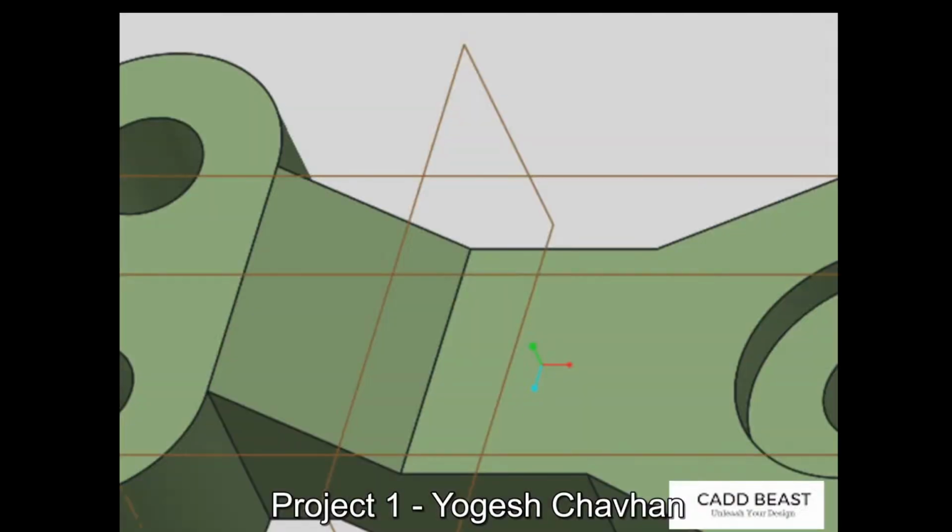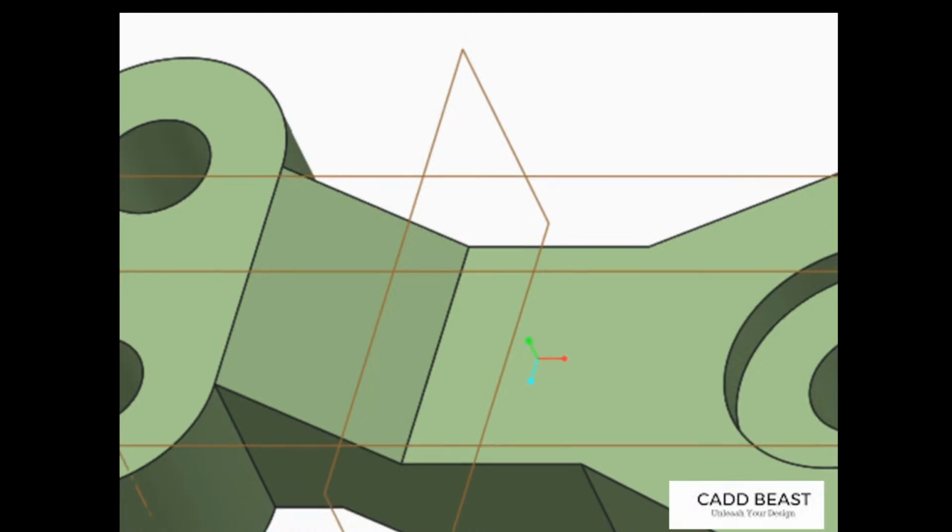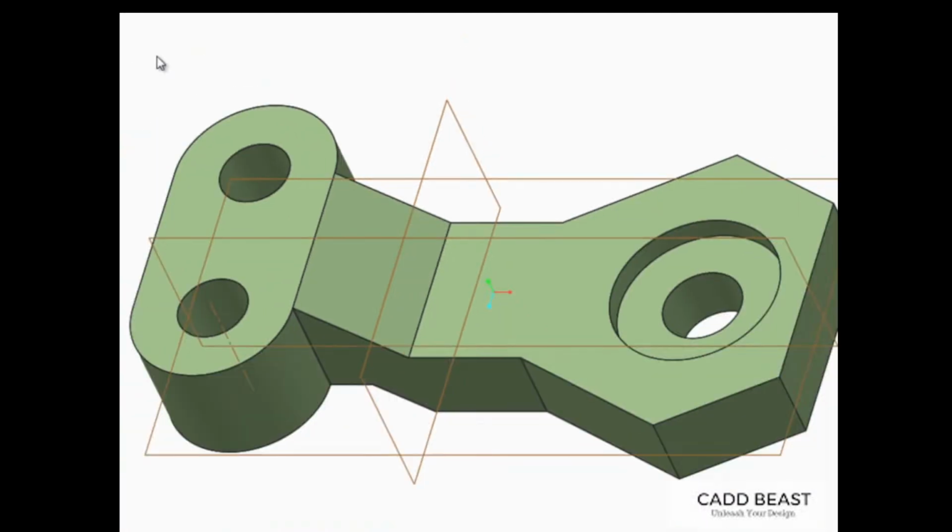Datum planes are 2D reference geometry. They have no mass and are infinite in size. In Creo Parametric, datum planes are typically used as construction geometry for features or as a reference when assembling components. The right, top, and front datum planes included in all the default template models are known as default datum planes. Every feature in a model is directly or indirectly created with reference to these 3 datum planes.